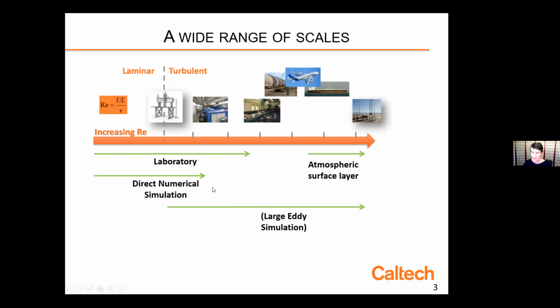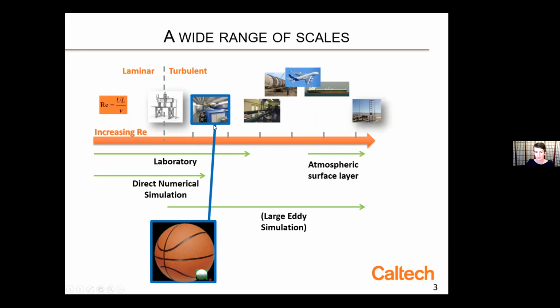So why this gap? Well, if we look at the range of scales that's observed in a wind tunnel, in fact, this wind tunnel, a flat plate experiment there, we'll find that the longest coherent structure, so the longest region that we need to be able to capture in any observation of the flow or simulation, is something like 2 basketballs in length. The thickness of the boundary layer, that region of adjustment from the surface of the wing to the quiescent air, or in this case from the flat plate at 0 velocity to a wind speed over the top, is something like the diameter of a golf ball. And the smallest scale that you need to resolve is about the diameter of a red blood cell. So that's not quite to scale, but that's a reasonably generic wind tunnel facility.